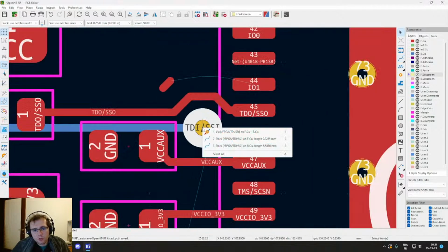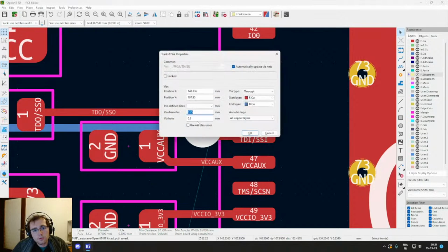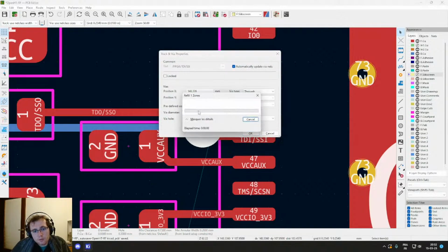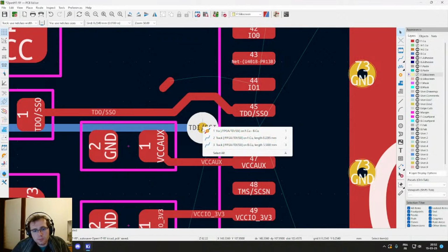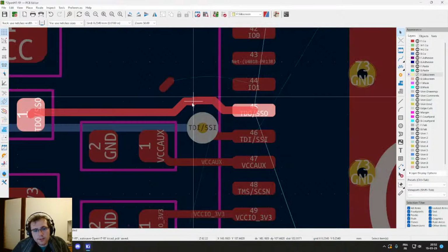I think I'm gonna need to use smaller vias, so I guess we can use, okay, maybe have a look at classic specifications for 4-layer boards, which would be about 0.2 millimeters drill and 0.2 millimeter ring, so like this, and this will be easier to place, and so we can do this.